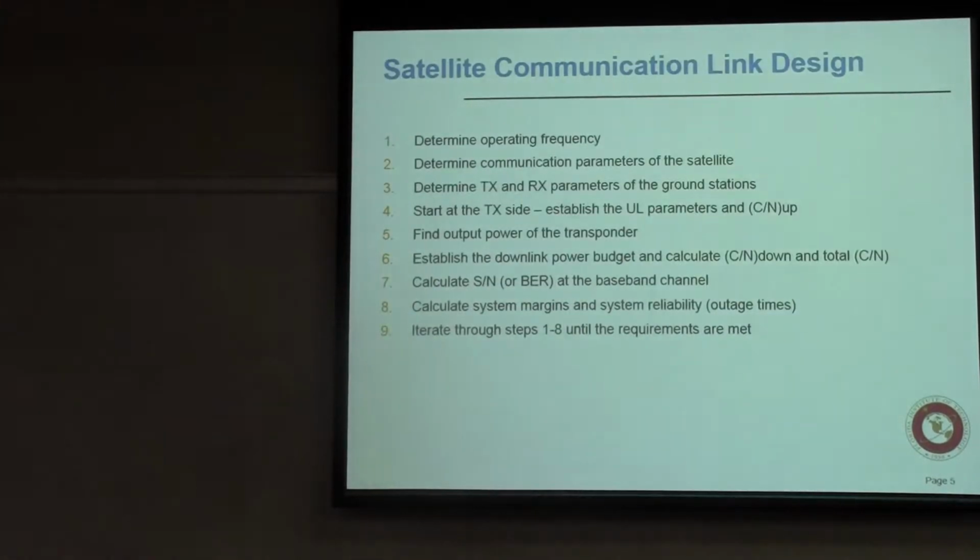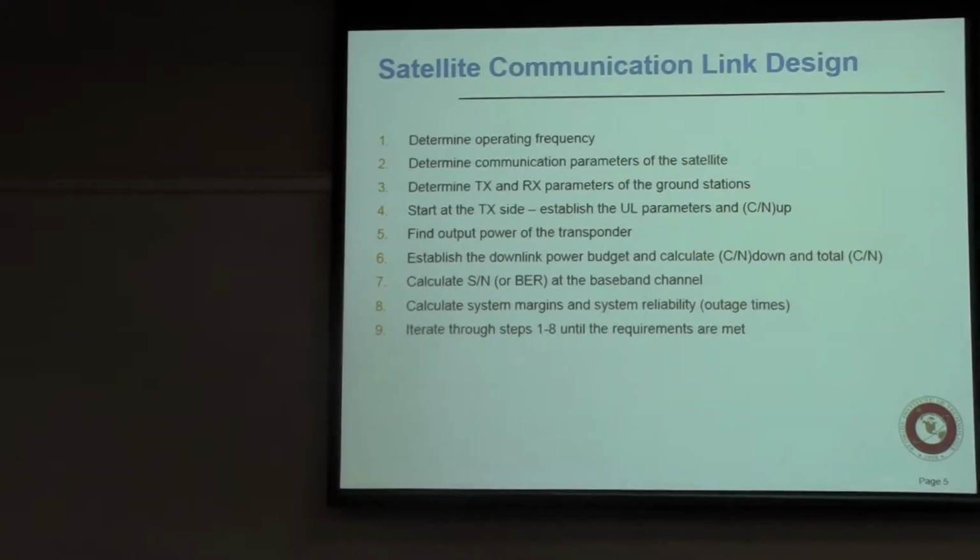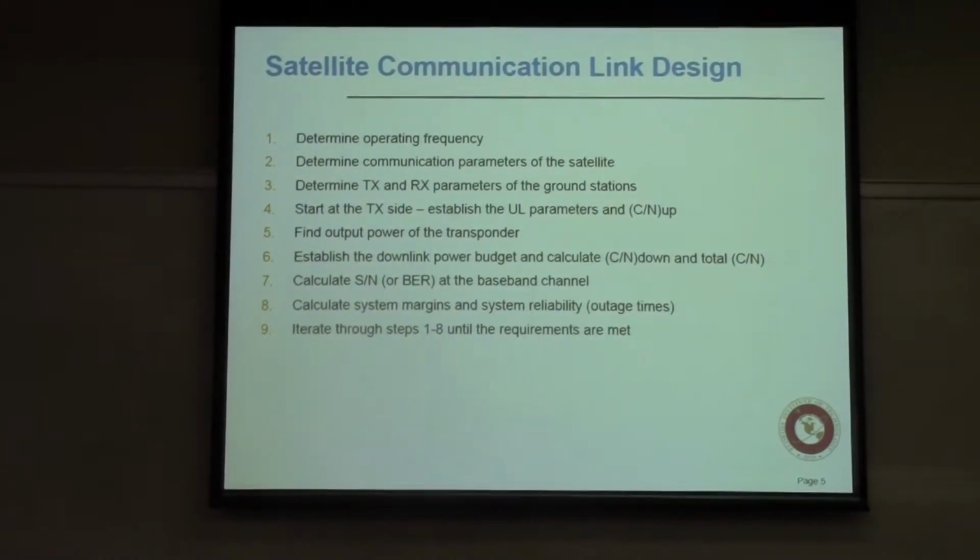Okay. So what are the components of the design? This is kind of following your book. You start with operating frequency, and that matters in several ways. It matters for the link budget, but particularly your margins are going to be very much dependent on the operating frequency, because different frequency bands have different exposure to the elements and variations due to atmospheric conditions.